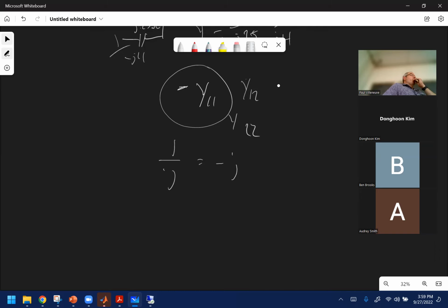More often than not, when you model in the real world, remember we talked about Y bus is just a model of the system. Load is not the system, that's the customers paying the bills. So our system is modeled as an admittance matrix, and doesn't have anything to do with power. It doesn't even have voltage or current. We talked about those current injections, we always would put those on the outside. If you want to make it a constant impedance, you can add those in there, but very rarely is that done unless maybe it's a 40 megavar cap bank that's going to be switched on, but that's a fixed impedance. So as the voltage goes up and down, it's going to put more or less reactive power on the grid.